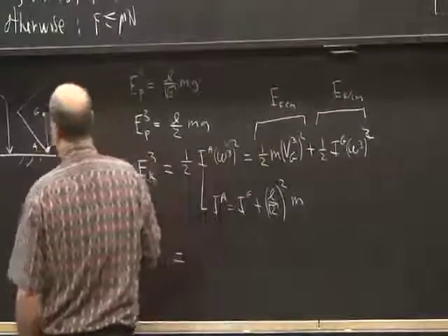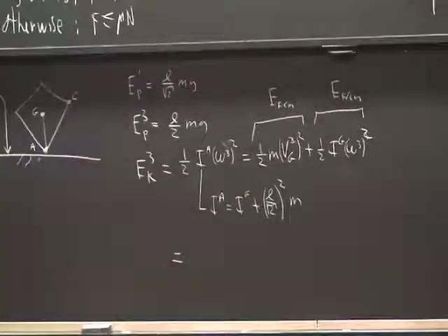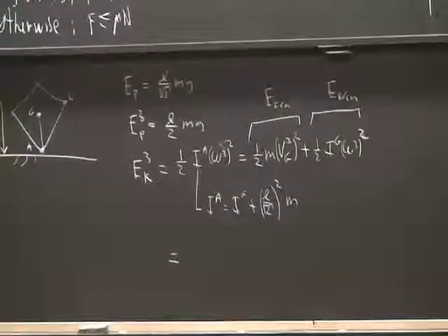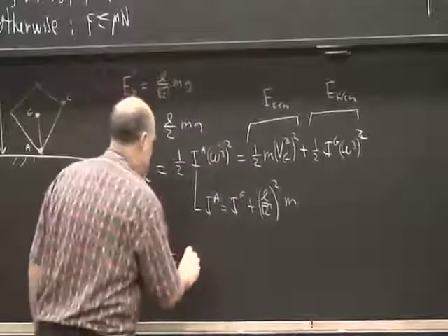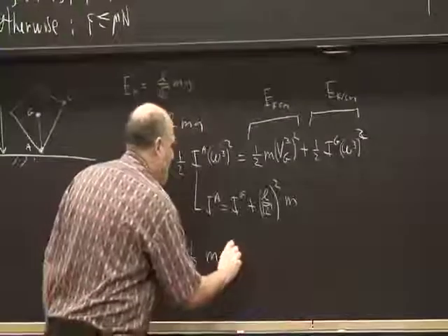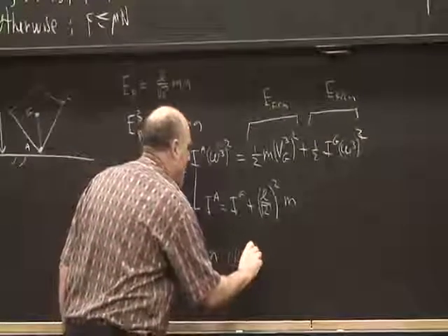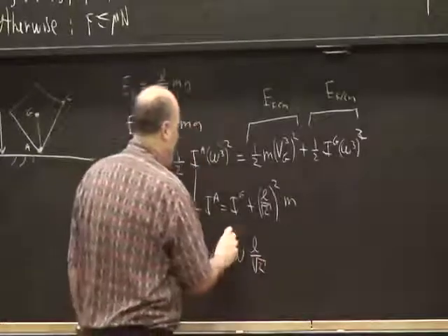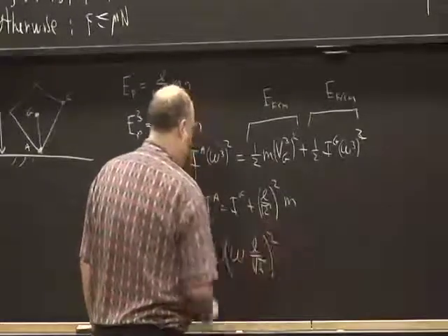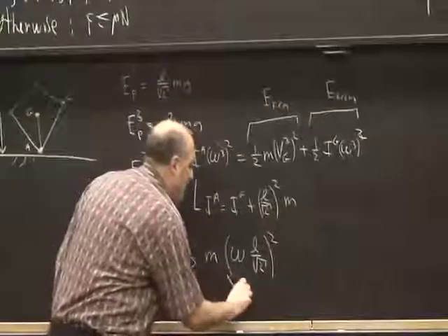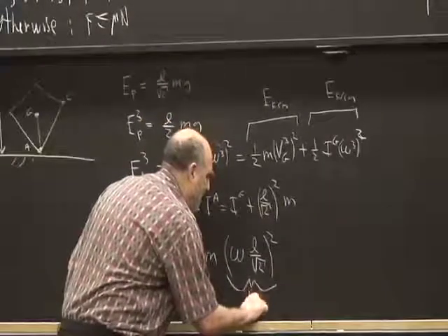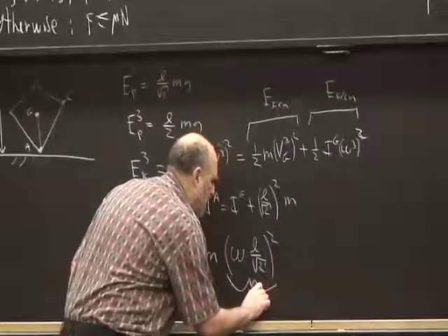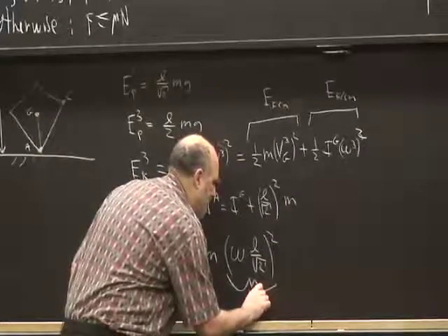So what is the velocity of this point G just before that collision? Well, it's the angular velocity times the distance of the point G from the point A, quantity squared. So this thing here is the magnitude of the velocity of G just before the collision, and that's in step 3.